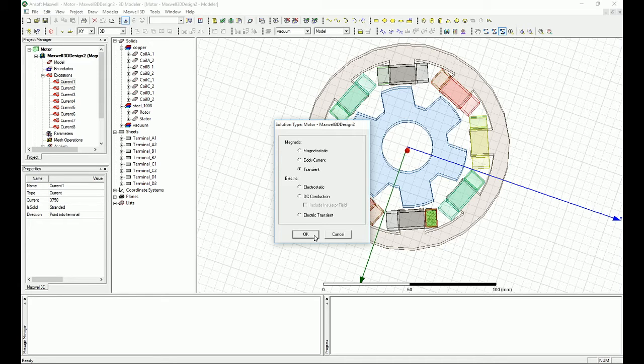You might ask, what are the coil terminal excitations? Well, the coil terminal excitations will excite a coil, and you can say the coil is a solid coil or a stranded coil. You can say the coil is excited with voltage, or you can say the coil is excited with current. One thing I have to tell you is that when you have coil terminals, you can have more than one coil for your windings. So you can have a winding and say, okay, this winding has 2 coils.